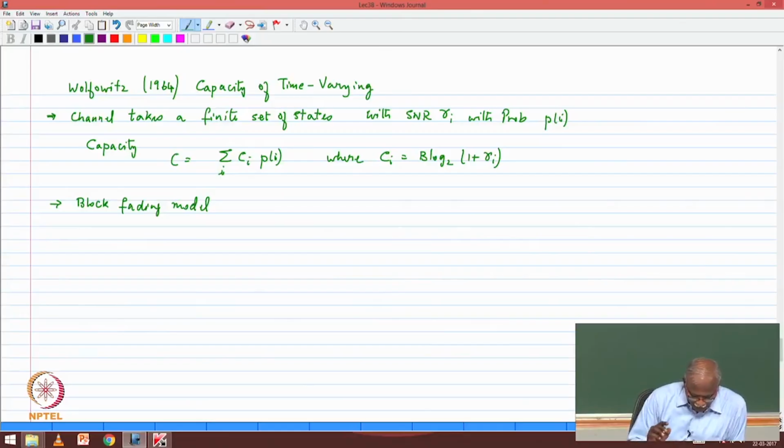Basically what we are saying is that you know what the SNR is that is occurring in the channel. We have no control over the alpha, what happens in the channel, but by allocating power, we can adjust the SNR of the effective channel. Okay.